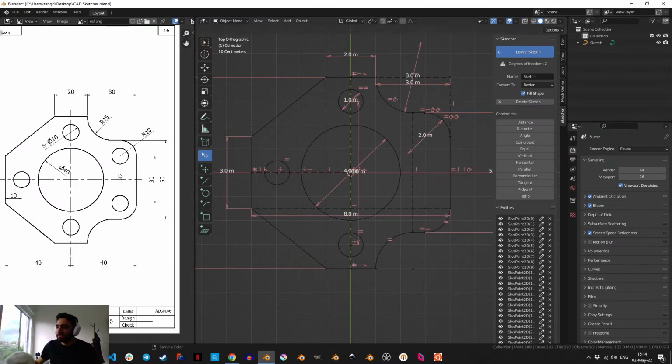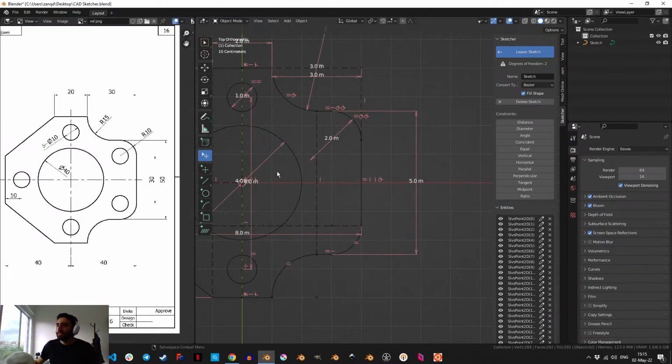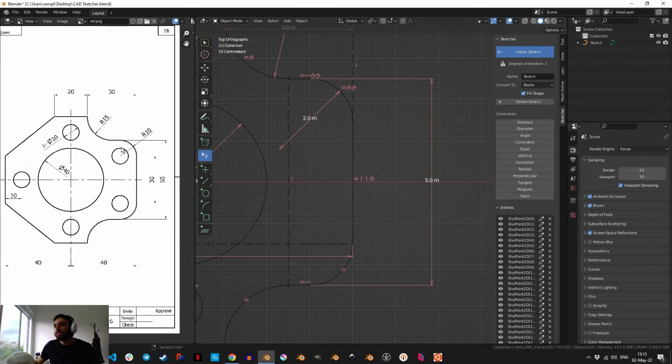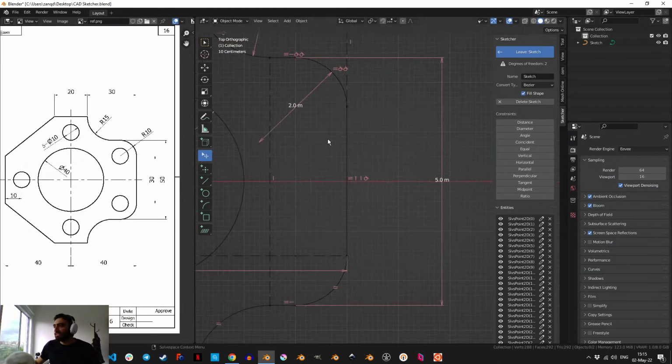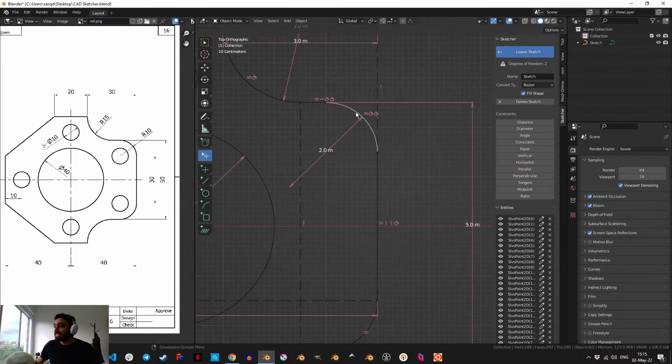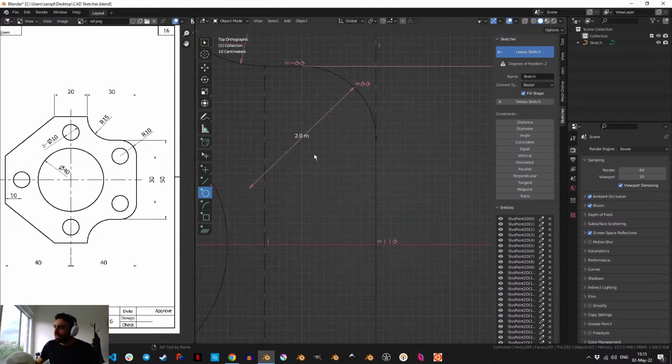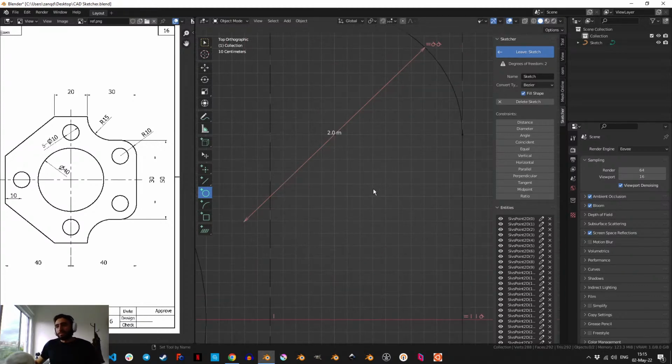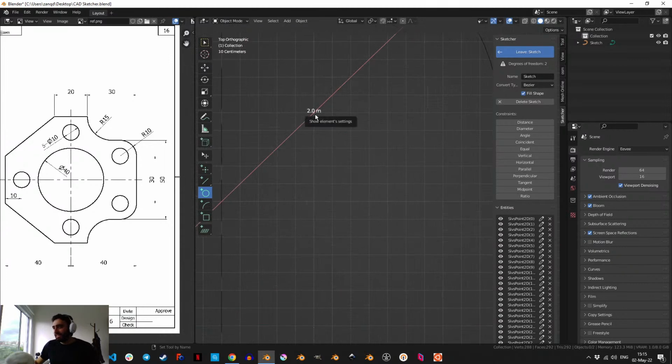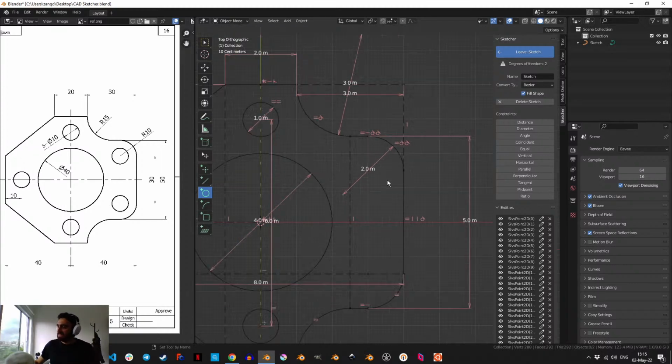And the last two, these ones are actually pretty easy because these circles can use the same midpoint as this radius. So all I have to do is go and create the circles. Oh no, well, it could be a little bit annoying if the constraint gets in the way, but there are workarounds for this.